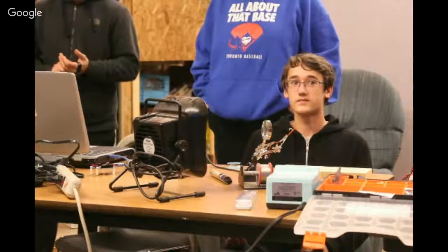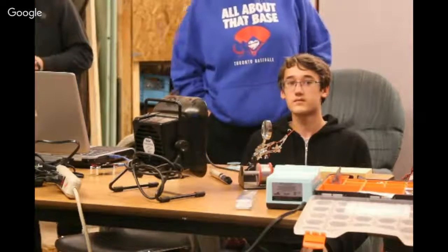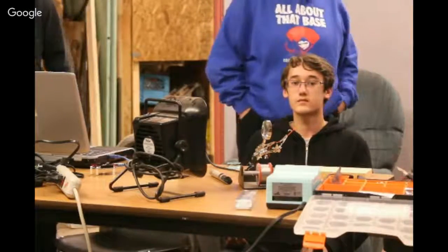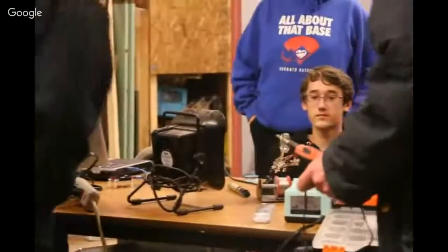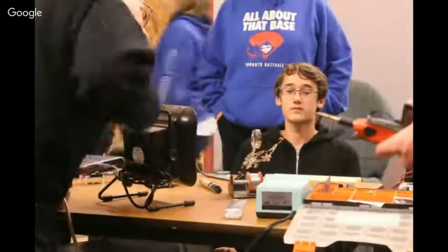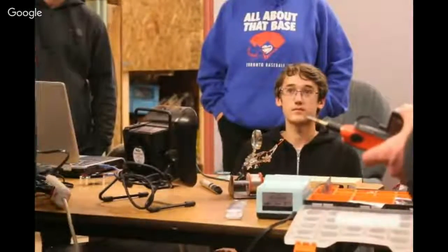Soldering irons. I brought one that I got from Canadian Tire or whatever, but it's just got one setting, right? Yep. Maybe that's not as good as this kind that you can adjust. Not as good, but perfectly usable for this kind of application. 90% of the time your soldering will be at exactly the same heat setting, and you pick one that works for you and just stick with that.